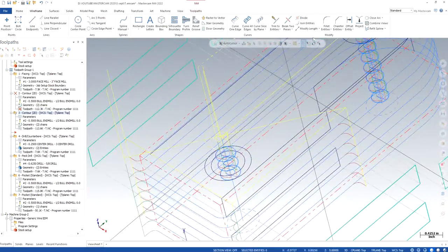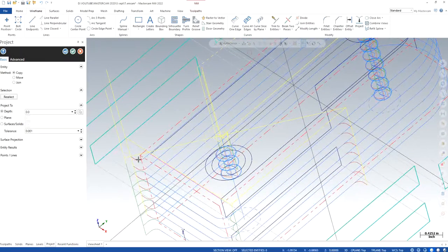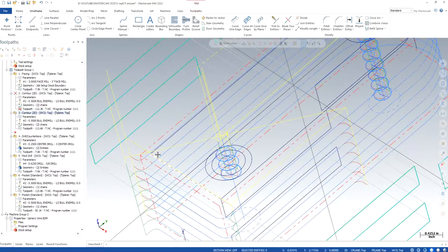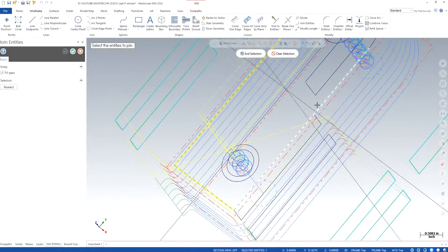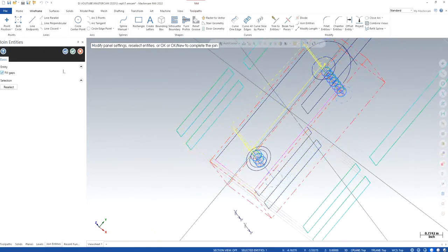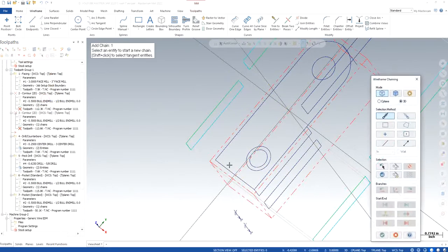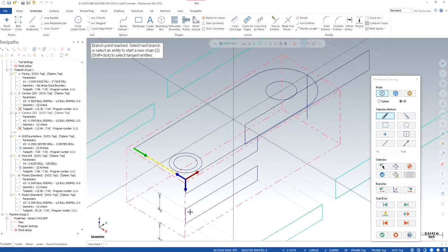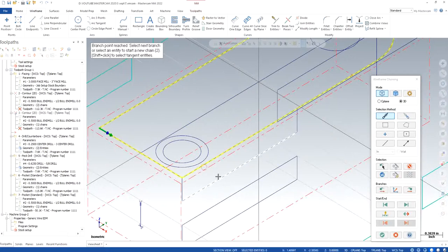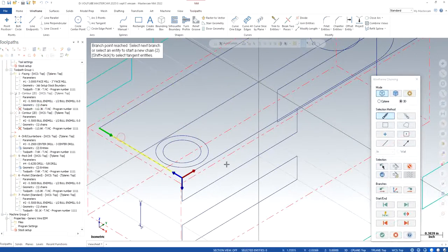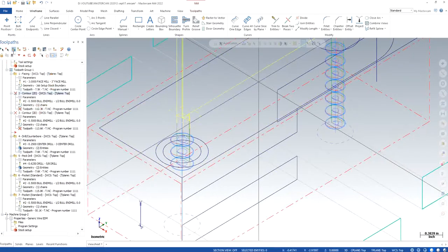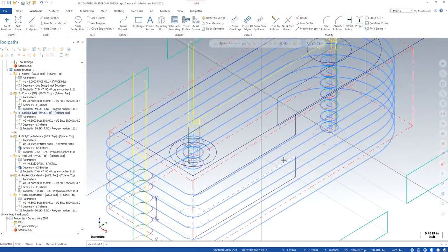Okay, I'm going to project this line. This line is important. This line projected at depth of this particular point right there. There we go. So now I'm going to join all these entities right there. Click OK. It should work now. Oh man, it's still showing as broken for some reason. One chain good. Same goes for the other one as well. Rechain all. One chain. Choose selectively. Looks fine now. Looks fine now. Alrighty.